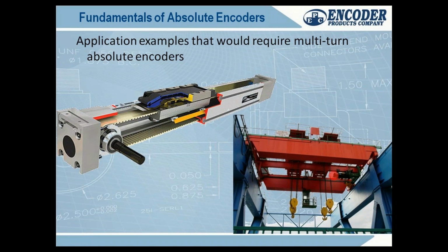Our encoders go out to 59 bits now of information. Imagine having a parallel output for that, 61 wires. So 59 bits of positional information. Just to give you an idea what you could do with that, you could actually put a 12-inch wheel on one of our encoders, 12-inch circumference wheel, like you're lining a soccer field, and you could walk to Mars and back 25 times before you rolled over to zero and lost your unique position.